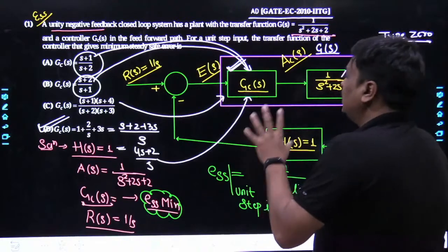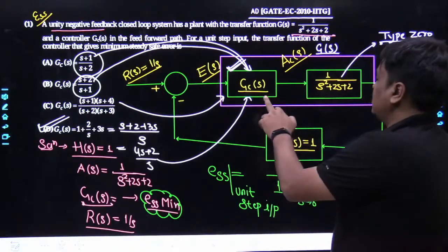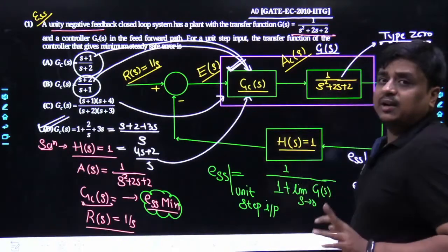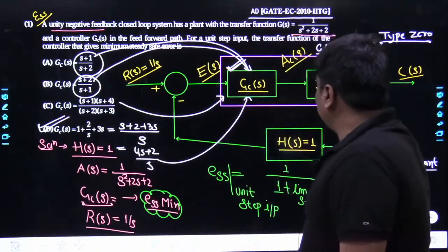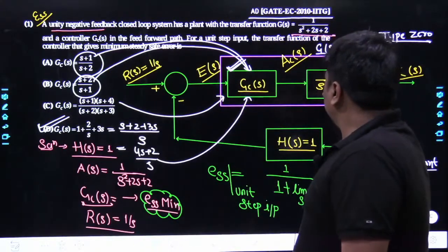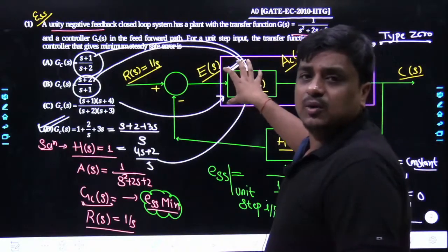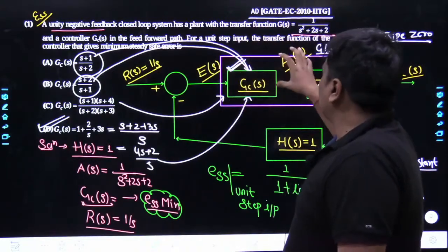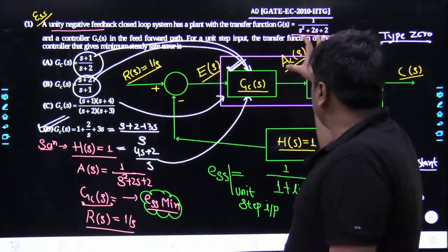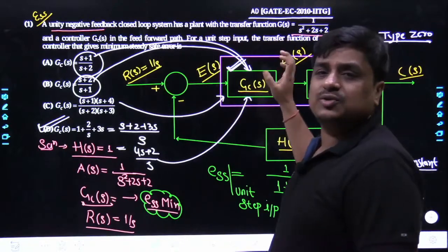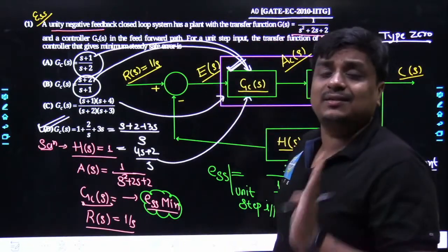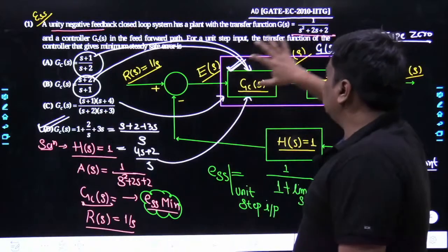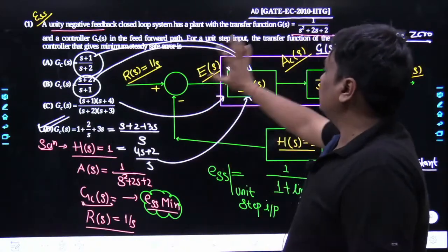Here 2 new terms have come into the picture. First is the controller and second is nothing but the plant. The persons who have gone through my earlier videos know I call it the control process. The input to the control process comes from the controller, and the output from the controller is also called the actuating signal, whereas the input to the controller used to be an error signal in a standard negative feedback system. So this was a complete structure.